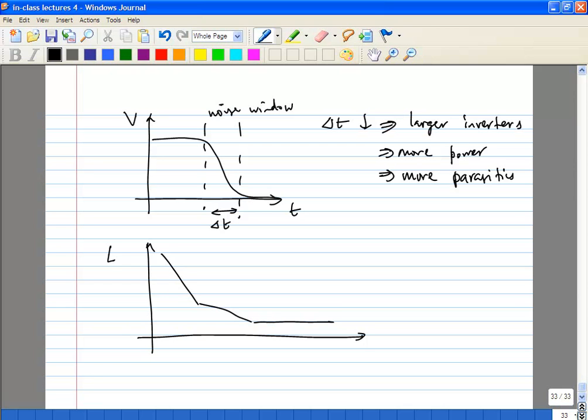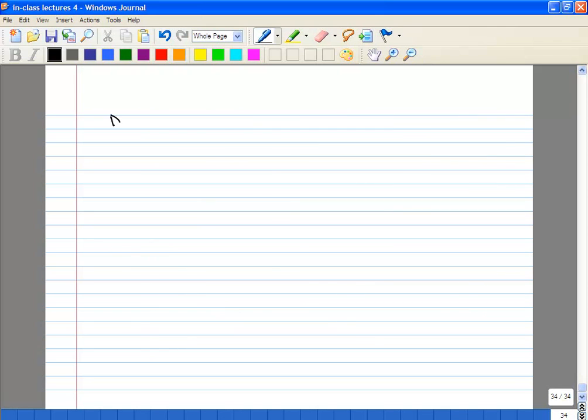Right. So this is just your noise floor. And why does this buffer noise matter? Why do you care about noise very far away? When we talked about phase noise, we talked about how when the phase noise is very large, and when you have in-band noise, that could desense your receiver either from a nearby transmitter or from an interferer. But we never talked about why your far out noise matters. So if you consider duplex systems where you are transmitting and receiving at the same time.